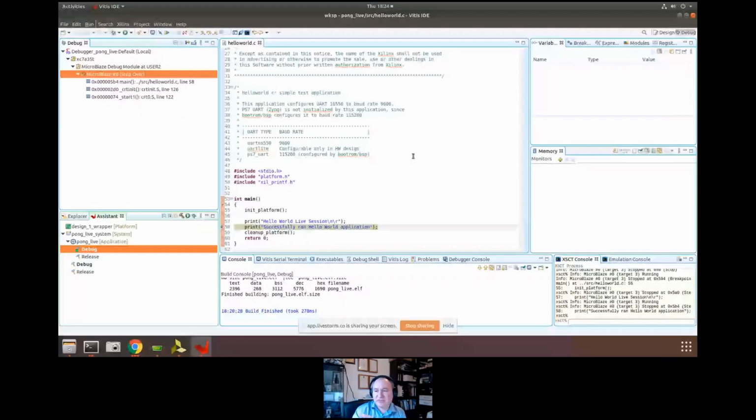And I can see in the chat there is a bit of a debate about why that address begins at 0x4. That is the address that's set by the MicroBlaze architecture to look for peripherals on the AXI bus. And I think Rui made a good point that the ARM architectures do it. So I think it's very common for commonality purposes. I think the MicroBlaze is set up to behave in a similar way, even though it's not an ARM core, it's a Xilinx developed core. But obviously, the more commonality there is in the environment, the better and easier it is for us to work with it.